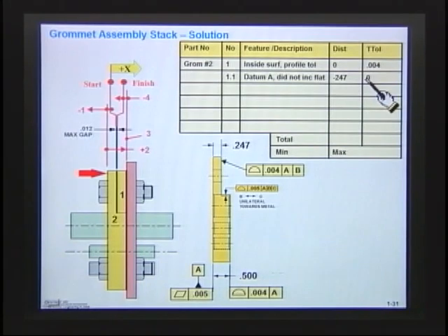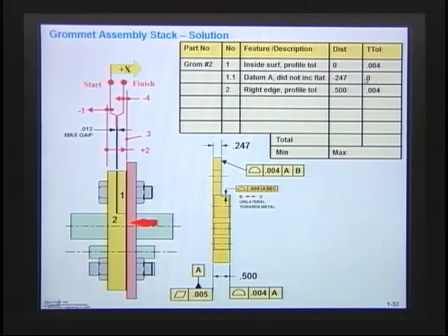All right, let's continue on our stack path. Well, let's see. There's our stack path now. And this one here is going to be number 2. Now, why it's number 2 is because we've already done that surface over there, right? That was the 1.1. So this vector number 2 is composed of 2 features, that feature and that feature, but that feature was already done. We did that with the 1.1. So what we have now is that feature right there. You see what that little pokey arrow is pointing to right there? It's that feature.